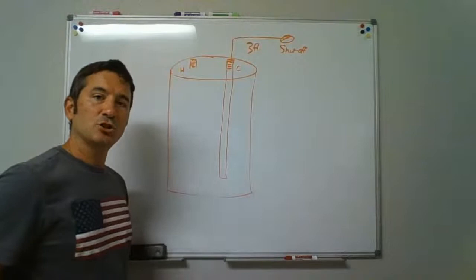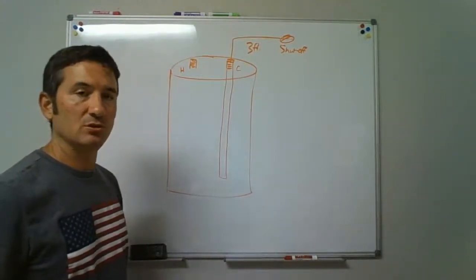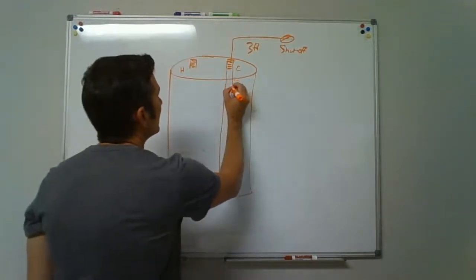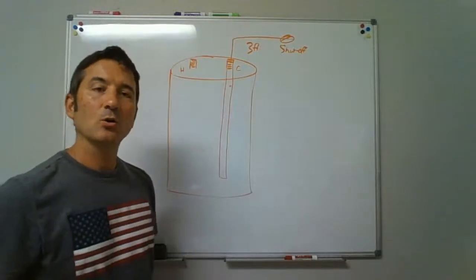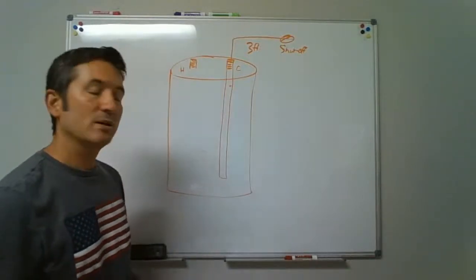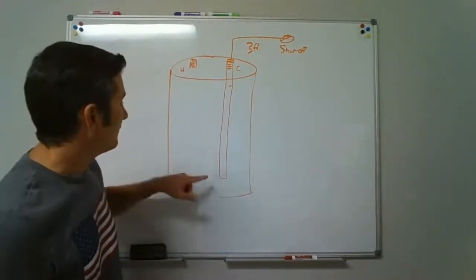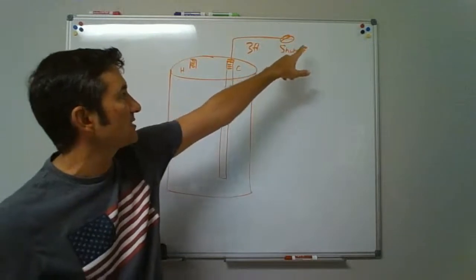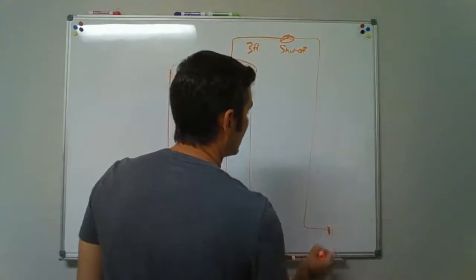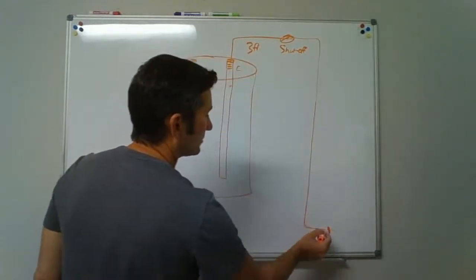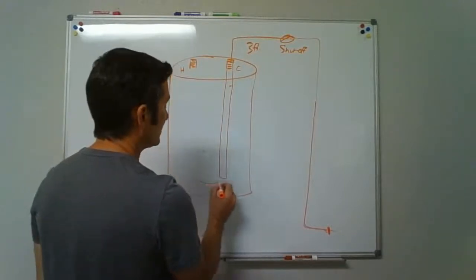Now, that tube is called a dip tube, it's a non-metallic, plastic material dip tube. And in the top part of that, there's a little hole. That's all it is. There's a little hole. And that hole is there on purpose. That is your anti-siphon device. Meaning that if we were to cut into this line, let's just say this line went over and went down and under like this. If we disconnect this line here and the water started to flow out and it was lower than our water heater, we could create a situation where water